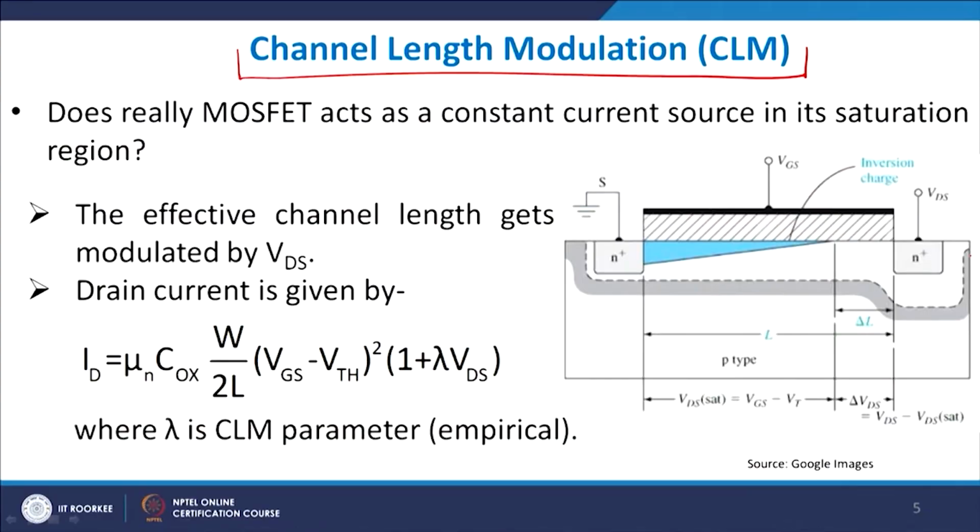See, in our previous discussion when we were discussing devices, we came to the fact that whenever you have a channel, in our case, it means that it has free charge carriers connecting source to drain, at least as much as it is n type as it was initially p type. That is what is known as the strong inversion phenomenon. Under strong inversion, you will have a direct connectivity path available to you.